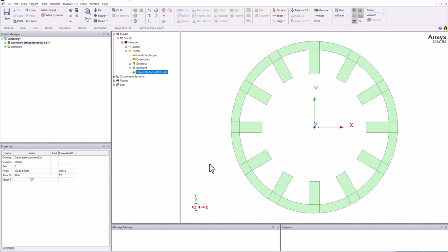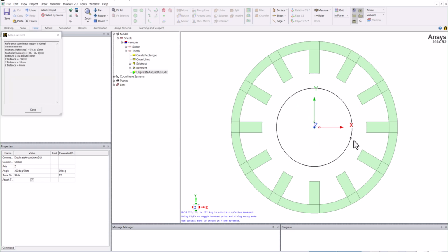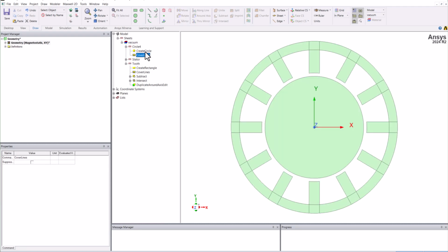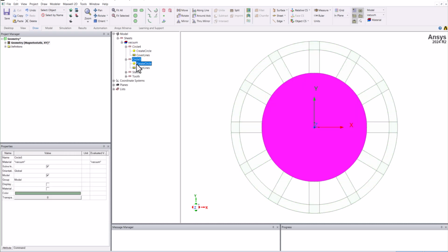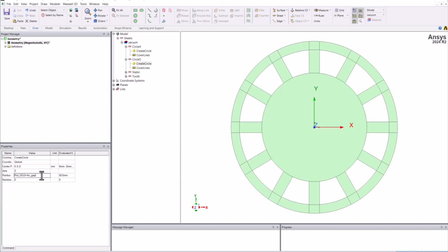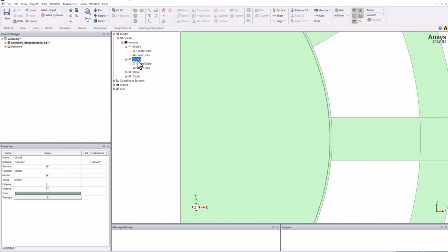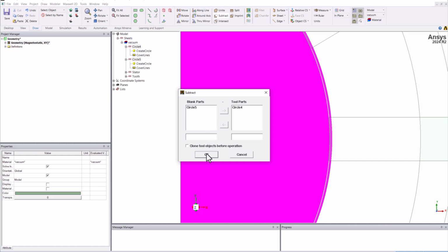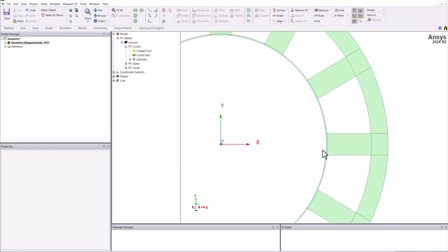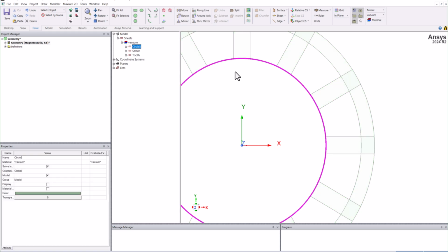Now we'll do another thing, which is adding the tooth tip. So here add rotor OD by 2 plus our air gap. We can copy paste also. So I'm just copy pasting, Control C and Control V, and this time I'm just adding tooth tip depth. So you see that we have two different rectangles. I will just subtract one from another, and now we have a ring representing the tooth tip depth.